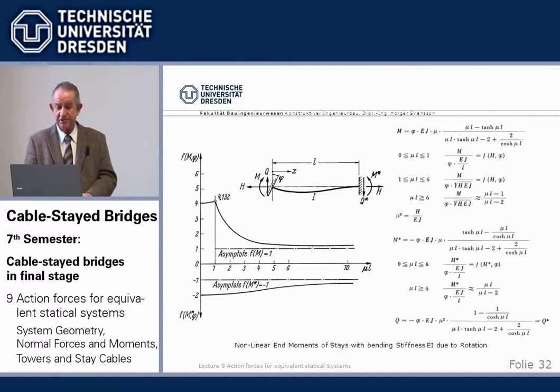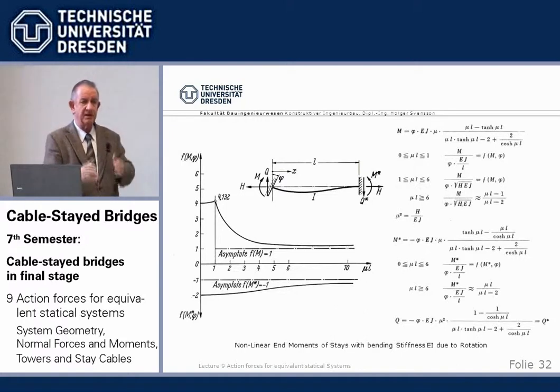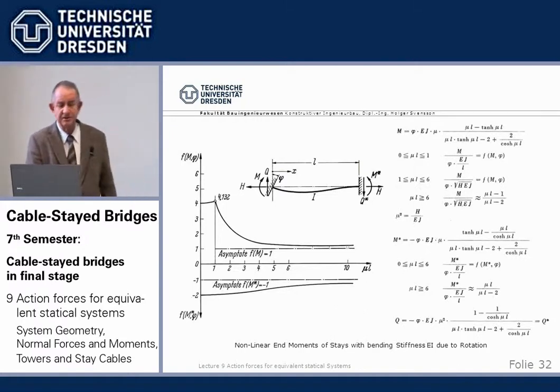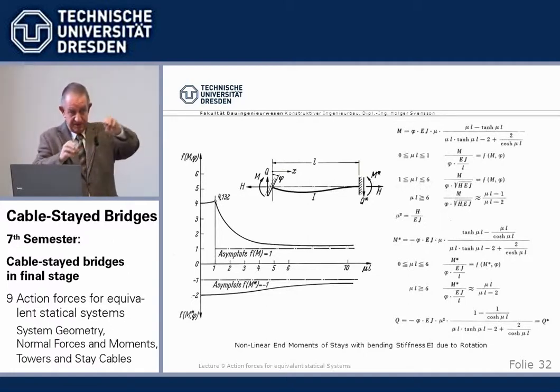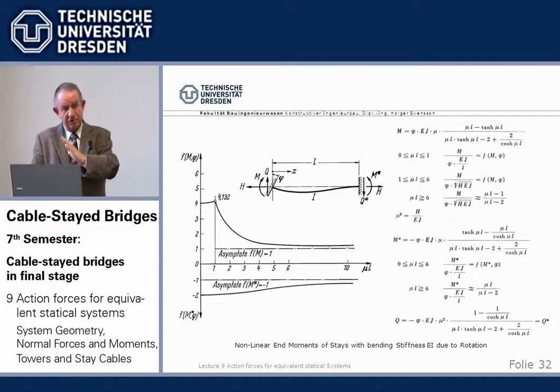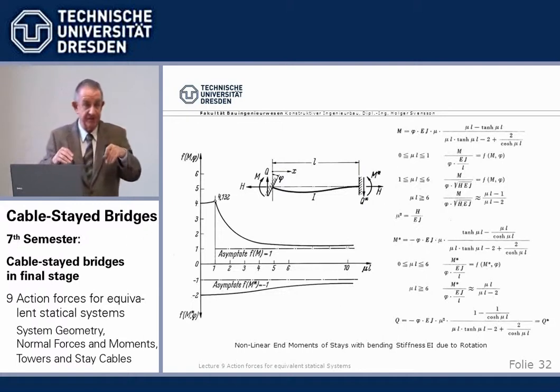Stay cables, very briefly. Of course, the main load for stay cables is the tension, and we size it by stresses, service or ultimate. However, if we have the tension cables and then the anchorage rotates because the beam bends due to high live loads, or if we have not installed the cable anchorage in the tangent, we have a sag cable, so we have installed at the tangent, not at the secant. There are examples where they've made this mistake.